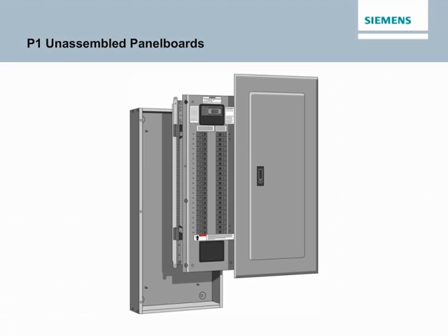The box is symmetrical, which means it may be mounted with either end up. The box is pre-punched for optional, field installable, door-in-door, or hinge-style trims. The interior is symmetrical, allowing it to rotate to change from top feed to bottom feed. Easy to use main breaker and main lug kits simplify the installation of mains. Branch neutral connections are near the breaker connections to speed wiring and reduce clutter.